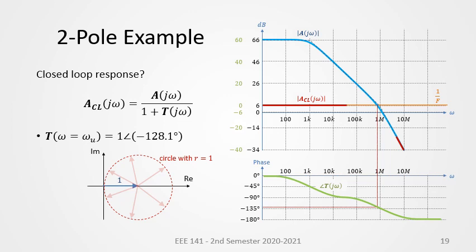phase we are considering. However, in the specific system in our example, the angle at the unity gain frequency is negative 128 degrees. We can also indicate in this figure the phase margin, or the additional angle for the denominator to be 0 and the closed loop response to approach infinity.